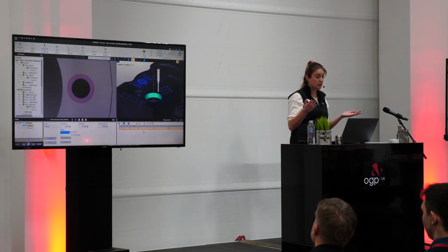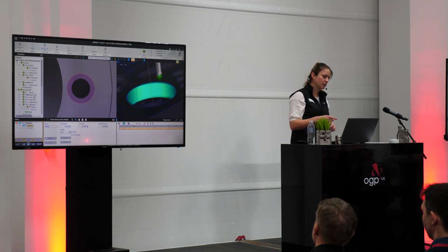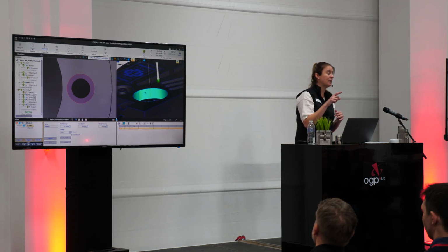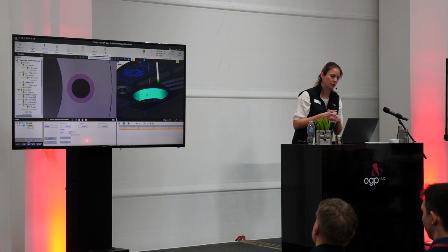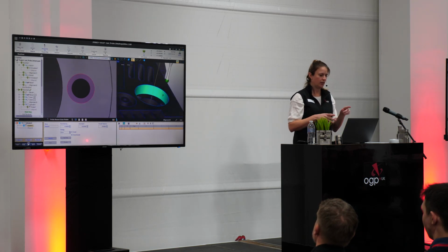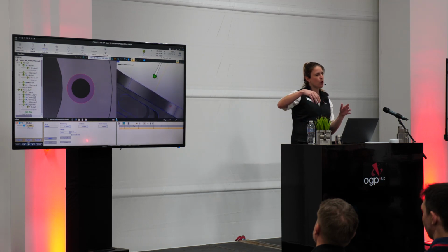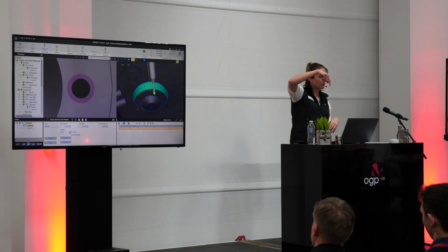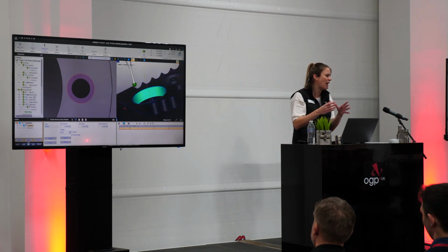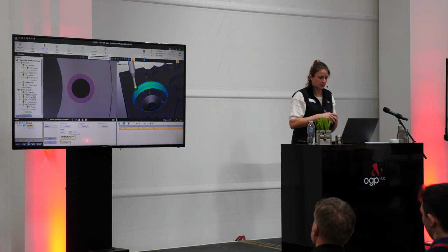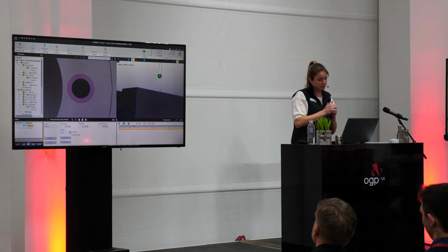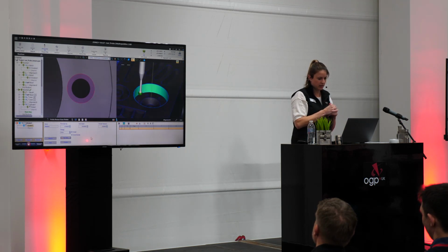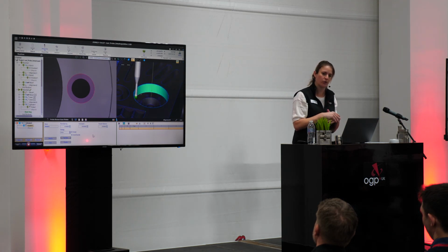So now we'll switch over to probe. It's the same thing. So here I'm going to click points on the CAD model for where I want the probe to take points. And over in the image window, since we're using a probe that's off-axis, you're actually seeing a simulated video image of where on the part the probe's over, so you can drive around easily. So again, if I want to use my path generation function, I can click there and it will automatically create the path for me as opposed to manually clicking on the CAD model where I want to measure.